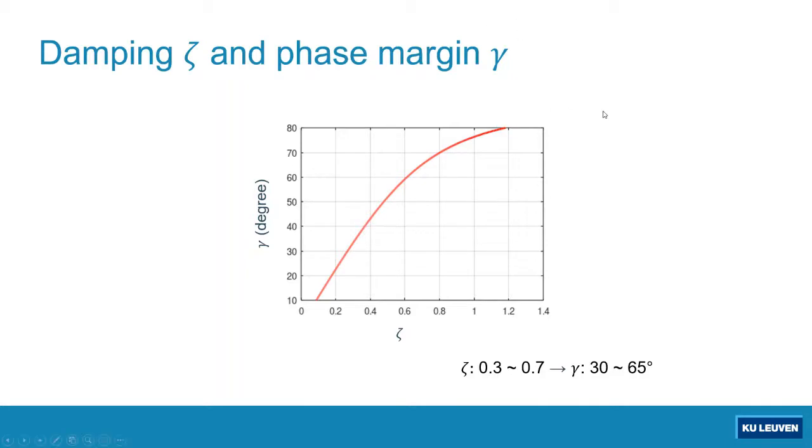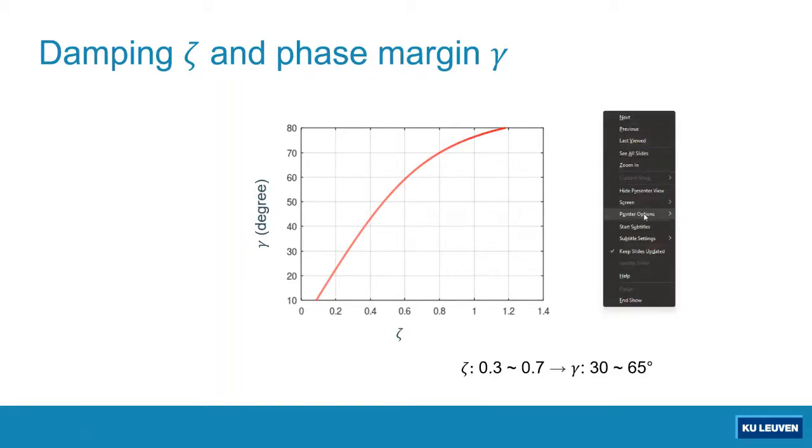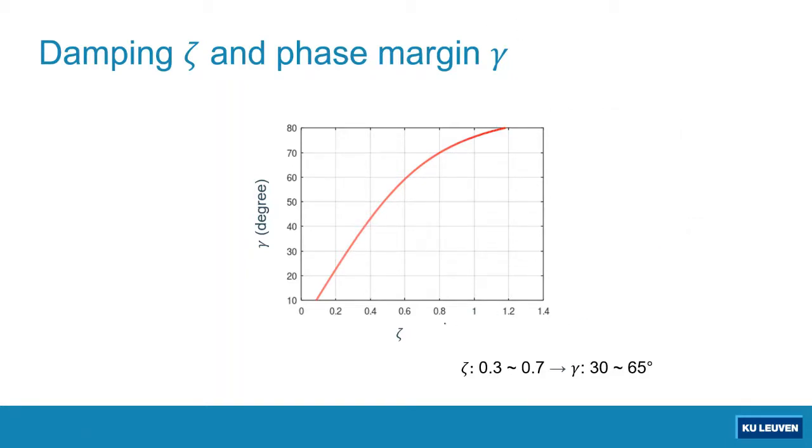When we want to have damping ratio zeta less than 0.707, probably it's somewhere here, this will translate to the requirement of phase margin less than 65.53 degrees.